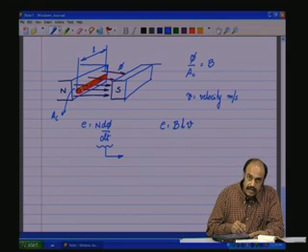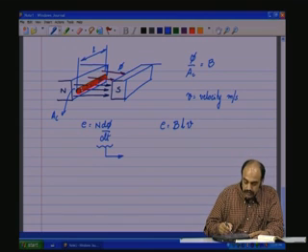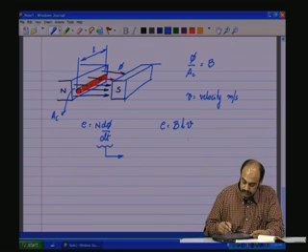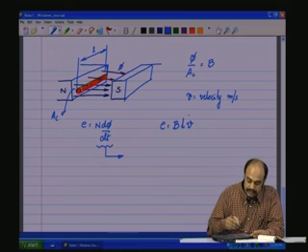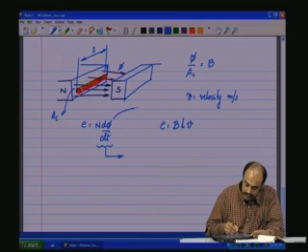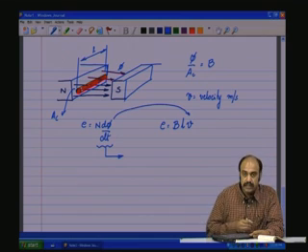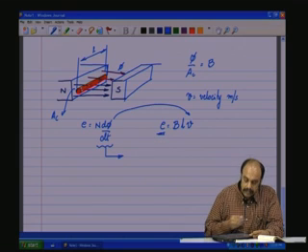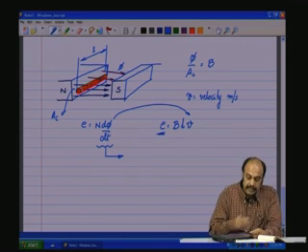As it is moving, it is at various radial distances, angular distances from the center, and thereby the flux amplitudes are going to be varying at different positions, and that is going to cause the d phi by dt effect, and it is going to result in an induced EMF in the conductor.